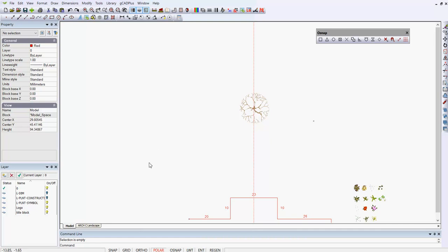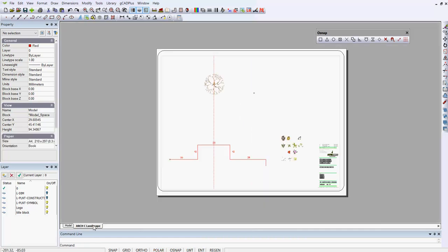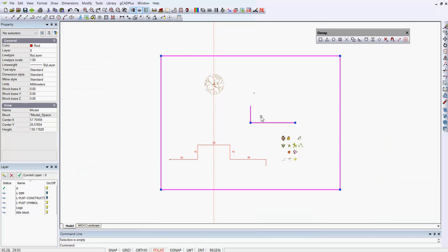Well, if I move back again to that layout sheet, notice that we've got a lot of information on the right hand side. Some of these symbols, they're not part of the design as yet, and I'd like to display the house footprint in our new design at the maximum magnification that I can on this sheet. To do that, to change my view, I just double click anywhere in the sheet and up pops this magenta box.